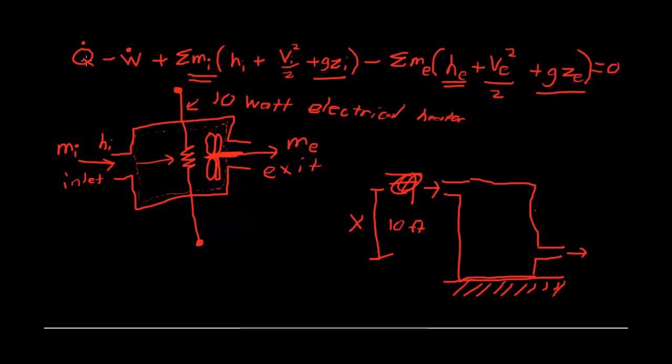So we looked at the Q term, the heat transfer term, the work term. We had an example of a mass going in. I could have, maybe I've got water entering here. Maybe I'll also have an inlet here where I have, I don't know, oil going in. And that summation sign just says, hey, you can have more than one mass flow crossing into the boundary. Or I could have more than one thing coming out. Right now, just have water coming out. Well, maybe I have some oil coming out over here at this exit. Maybe that's exit 2, and that's exit 1. That's inlet 1, and maybe this is a second inlet. That's what that summation sign is for.